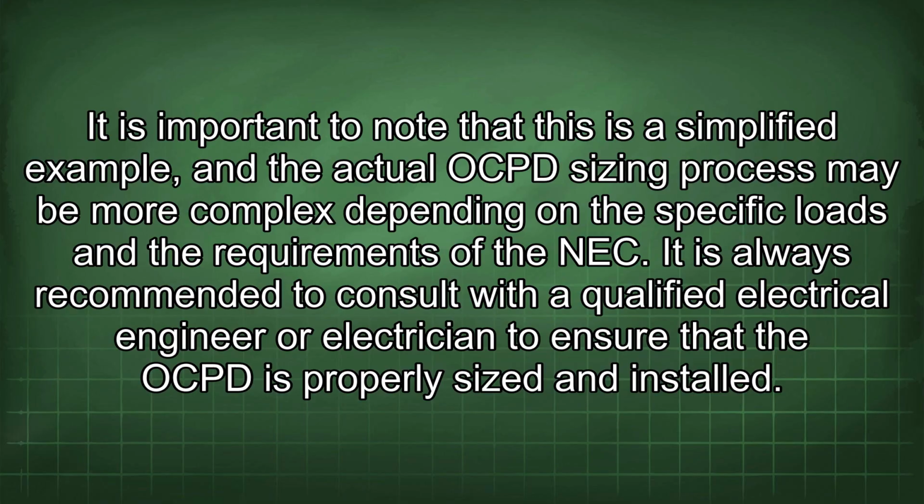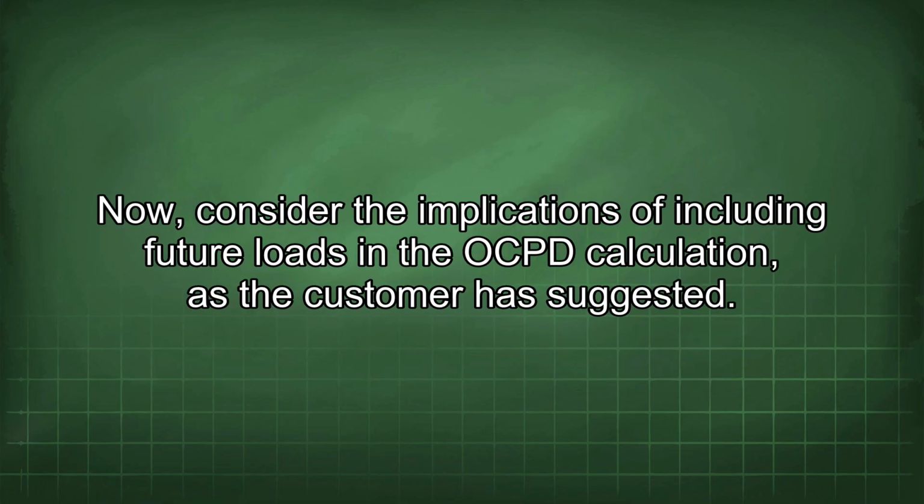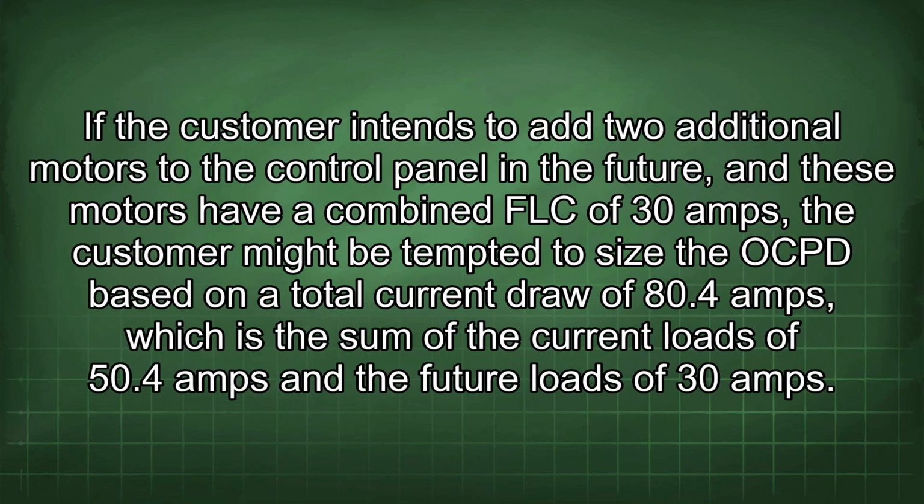It is always recommended to consult with a qualified electrical engineer or electrician to ensure that the OCP is properly sized and installed. Now consider the implications of including future loads in the OCP calculation, as the customer has suggested. If the customer intends to add 2 additional motors to the control panel in the future, and these motors have a combined FLC of 30 amps, the customer might be tempted to size the OCP based on a total current